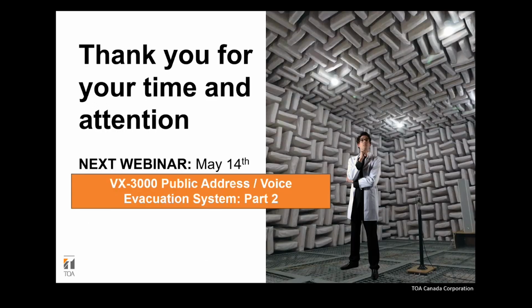When do we use the IPA1? Yes, so the IPA1, if you have an existing VoIP system or a SIP-based system, it works really well. We can use the IPA1AF as an endpoint and then use that as a bridge to connect onto the VX3000 to feed the PA system with audio and contact triggers if you need that.